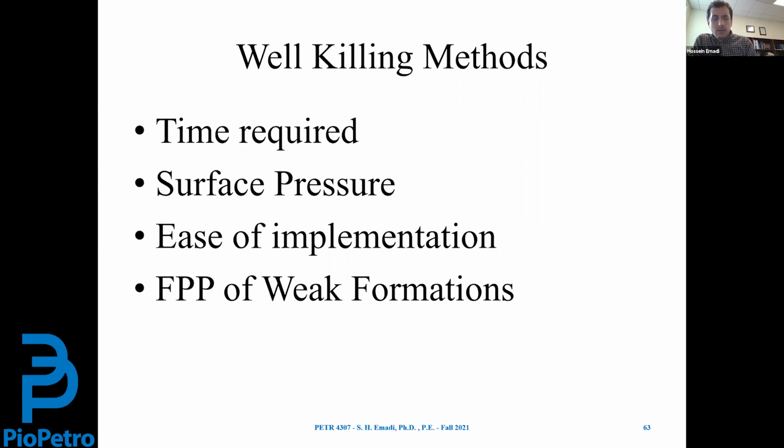Ease of implementation. Sometimes it's quicker to kill the well using the wait and weight method. However, the drilling personnel is more comfortable implementing the driller's method. In this situation, despite the fact that the wait and weight method is faster, because we want to always make sure that we complete the operation in a safe manner, because safety always comes first, we implement the driller's method.